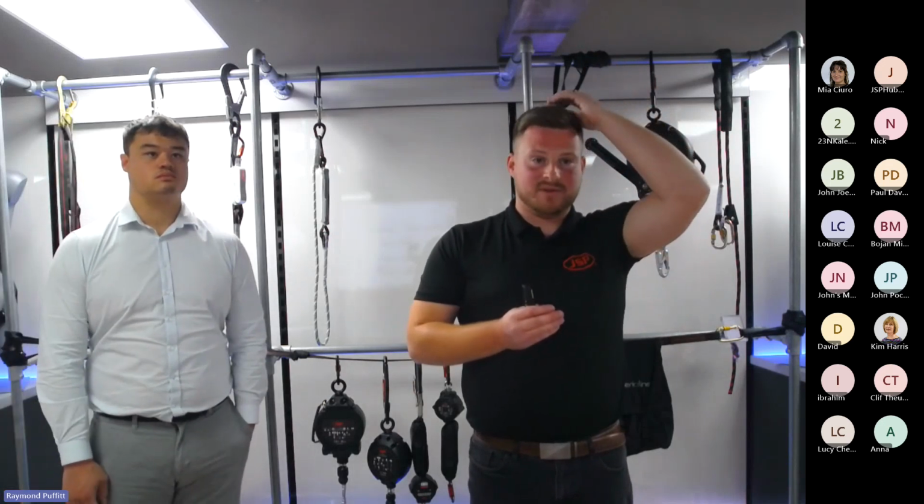Fall arrest blocks are different, because with standard fall arrest blocks, a lot of the time you're connected directly above you, so the chances of needing it for a sharp edge is different. But if you need it for horizontal use, that's always going to need the sharp edge testing. I'd imagine at one point we'll get rid of the standard fall arrest lanyards and only have sharp edge tested lanyards because of that.